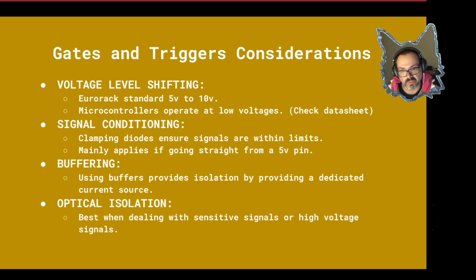And that's going to make sure that your signal stays within whatever you clamp it with. So ground and 5 volts in our case. Okay. There is one gotcha there. Depending on the microcontroller that you have, you may not be able to have enough current to drive something down the line, another module, for example.